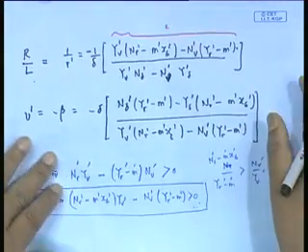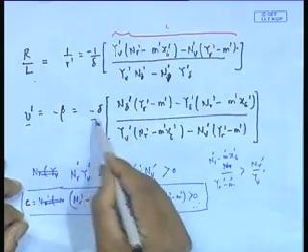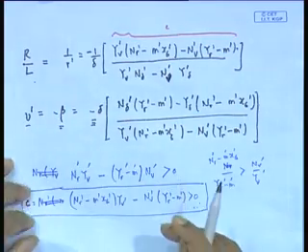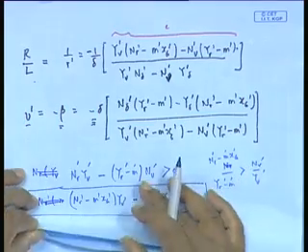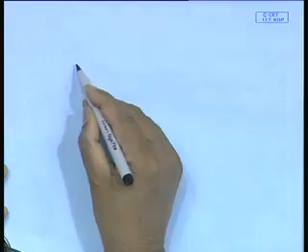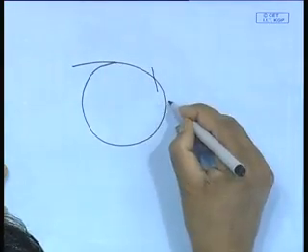That is point 1. Point 2 is with respect to the drift angle. I will leave it to you, but you will find that the drift angle is directly proportional to delta, which means that if I give larger rudder, I have larger drift. That makes it a very interesting point. If I give larger rudder, the ship turns quicker with a larger drift angle.